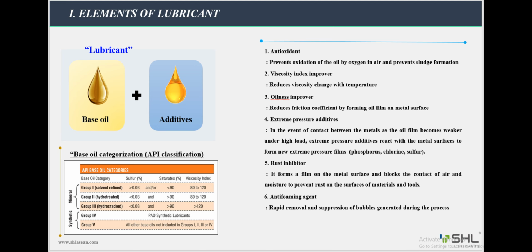Synthetic base oils are classified into Group IV and Group V, having more specificity and specific outstanding advantages than mineral base oils, but their functions are not as diverse. About additive composition: depending on the type of industrial oil, it is mixed with different types of additives.